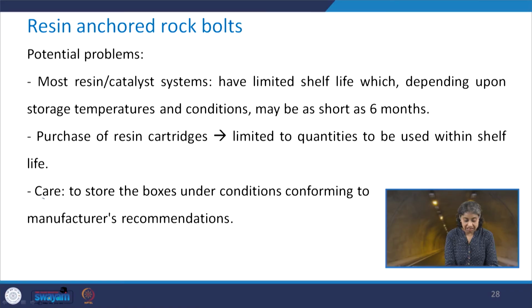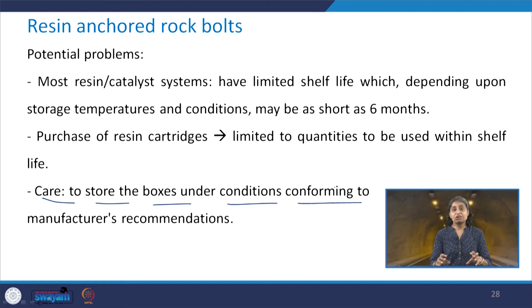One needs to be careful to store the boxes under the conditions conforming to the manufacturer's recommendations, because if you do not follow them, it may happen that you have installed the rock bolts, but they are not providing the kind of support for which they were installed.